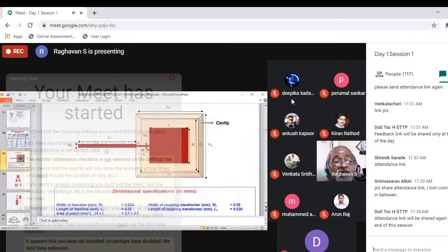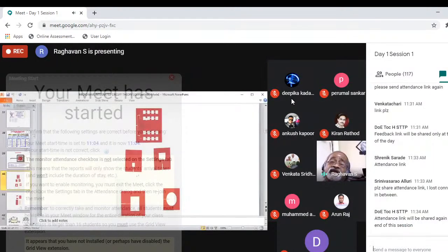The next one. Just like the conventional antenna, if one antenna's gain and directivity are not sufficient, then you can go for arrays. That's how you have this first one, an array of patches. And when you want to make the connections, you should go for dividers. For every divider, you make use of the formula Z0 squared is equal to ZS into ZR. That's how you find the length and the width. Finally, you should take care of discontinuities also: end discontinuity, gap discontinuity.